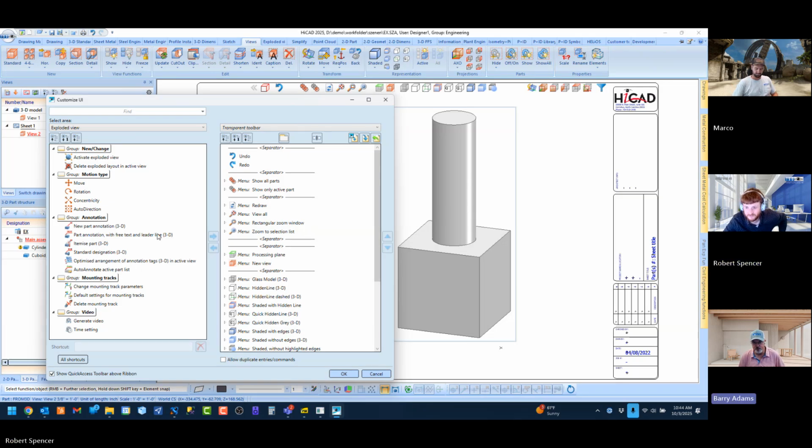Pretty sure it's any of these. Is there an alias list, or is it just keyboard shortcuts? What do you mean by alias? Maybe I don't quite understand. Alias, like for example in AutoCAD, the stretch command is S, and I changed it, because I use slice so much, I took over that S and just changed the alias. Now stretch you can always get with ST, or you can assign it something else. It's always going to be ST, but I'll just hit S as a keyboard shortcut for slice.